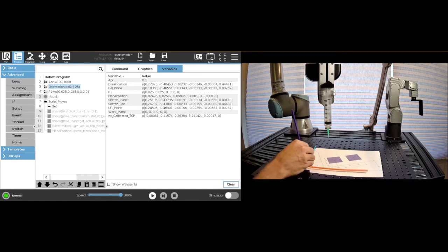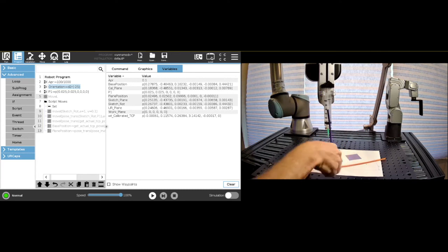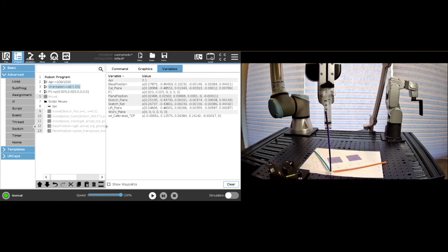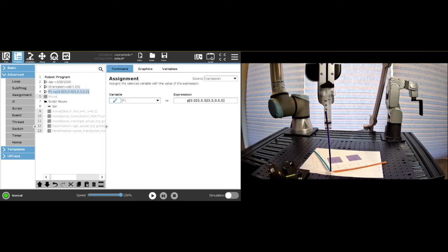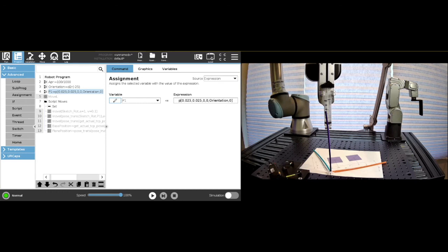And if we have here our axis, the way that the rotation works is that you put your thumb in the direction of the axis, and then curling towards your thumb like that is a positive rotation. So if we want this to be tilted like this, it is a negative rotation in the y-axis. So that's why we're going to put minus 25 degrees here, and we're going to set this point here to have that rotation for the y. So this is our ry here. So we go variable, orientation.